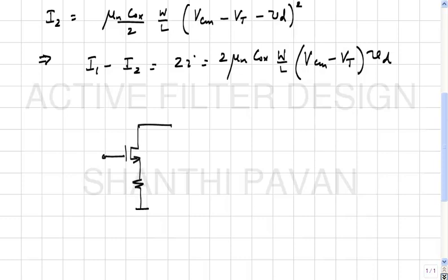So, this is the incremental equivalent of the common source amplifier with feedback. This is a feedback based voltage to current converter. Please note this is an incremental equivalent. This is not the complete circuit. So, what is the exact expression for the transconductance?